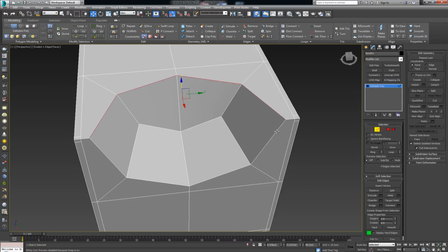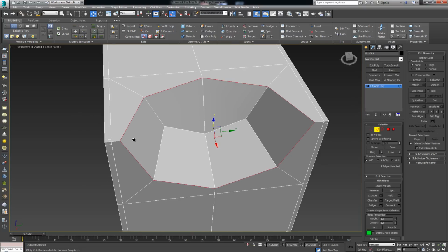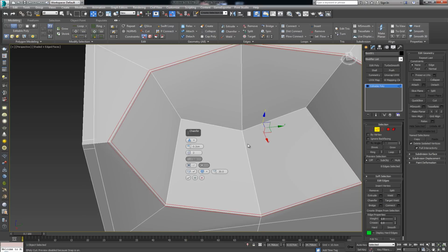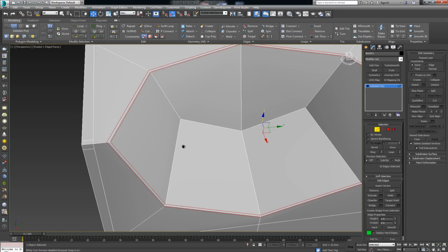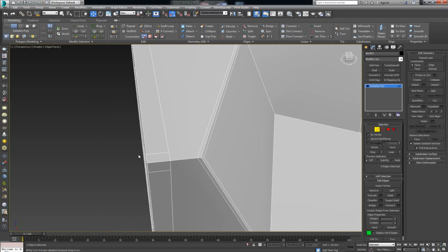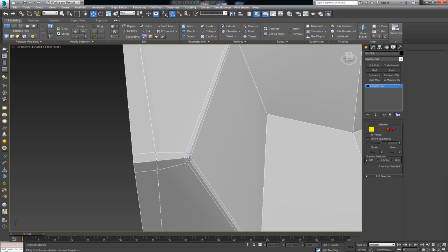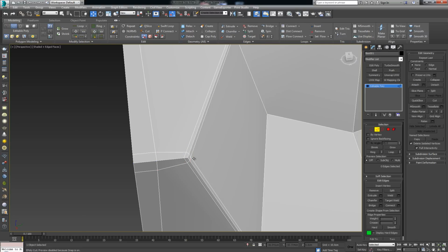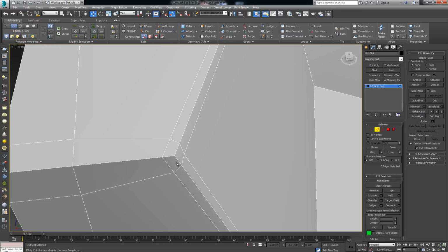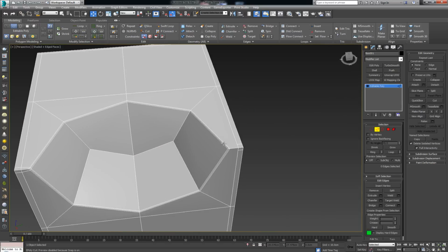So now I'm going to select all of these edges, chamfer them like this, 0.2, so we retain that sharpness we have on the other side. And again here, let's use the same trick that we used with the diamond for the edge. So from here, the outer one, inner one, center, outer, connect. Select this piece over here in the middle, Control Backspace, and as you can see, we have the diamond shape again.